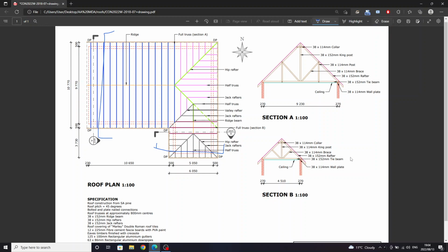We will scale, let's call this the shorter strut and the longer strut. You scale this rafter, and you're going to scale the collar, and since it's duplicated on the other side, you don't scale twice. That would be a waste of your time. You're going to scale this king post. For these smaller trusses, it's the same story. The strut, the king post or king strut, and the rafter you will scale, and the tie beam you'll calculate with the given values. You've got a collar here.